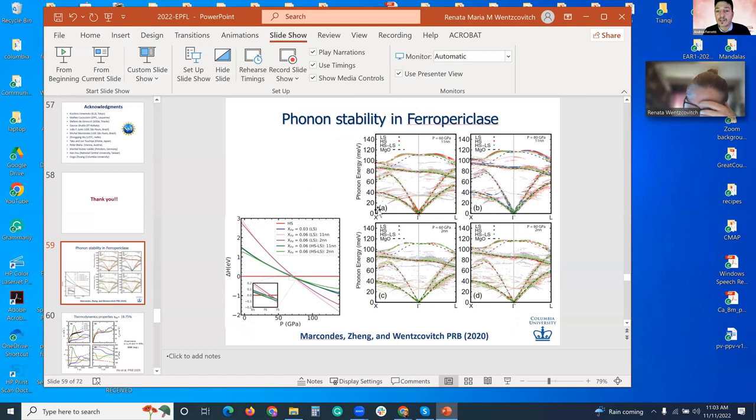That of course we can do within our simulations. So what is the reliability of our Quantum ESPRESSO simulations at these ranges? Can you comment on that? I think probably this comes back to pseudopotentials. Well, up to 135 GPa, iron with 8 electrons is pretty good. You don't need iron with 16 electrons. You need that above 150 GPa. You need iron with 16 electrons if you want it to be accurate.